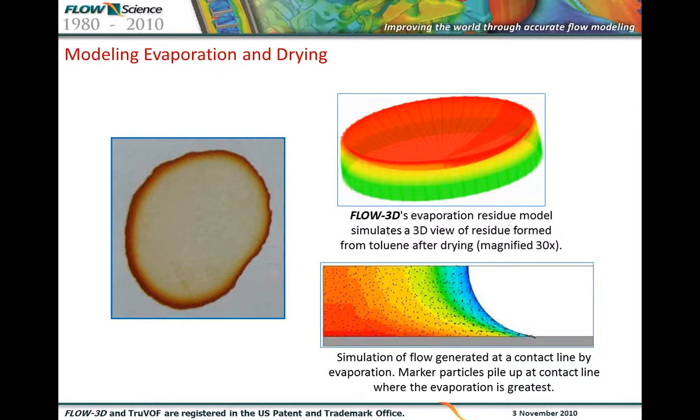Heat transfer from the surroundings causes the droplet to evaporate more significantly at the droplet edge. This effect, along with surface tension, causes a curvature at the edge. This in turn induces a net flow towards the edge as fluid flows there to replenish the evaporating fluid. This motion moves the solute towards the edge, building up a ring of solute there.